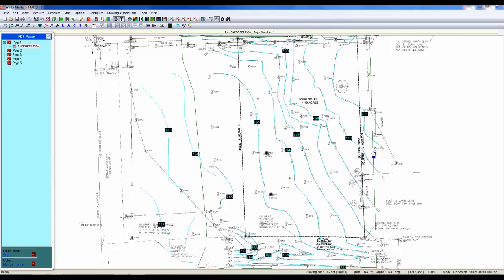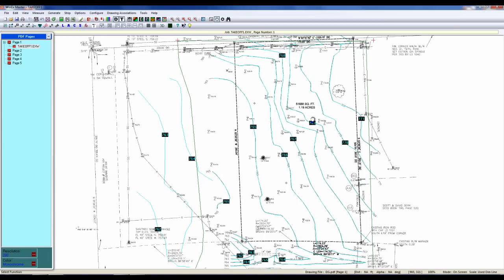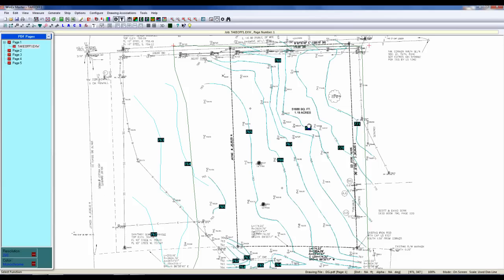And the way that we do that is we use two reference points, or what we call locator points, to overlay your takeoff lines onto an alternate page. And we can do that no matter if the two plans have different scale or are at a different orientation. And we're able to do that because of these two locator points. So I'm going to go ahead and demo to you how you can go about doing this.